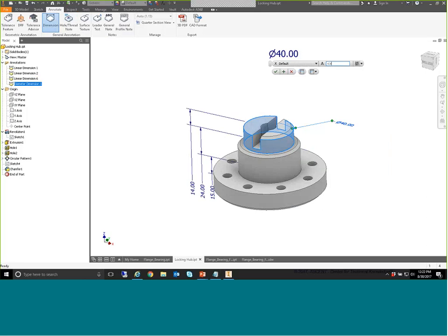And you can see now that I'm back in my mini toolbar. So again, you're going to see these a lot. I can actually add a symmetric tolerance to this. So I'm going to choose my symmetric option. And here I'm going to enter a value. So I can't select in the preview, but I can select in the mini toolbar. So I'm selecting that .00 tolerance field. I'm going to change that using that new mini toolbar that just appeared. I can also change my precision if I wanted to, and click OK. And you can see how it's added the tolerance value.